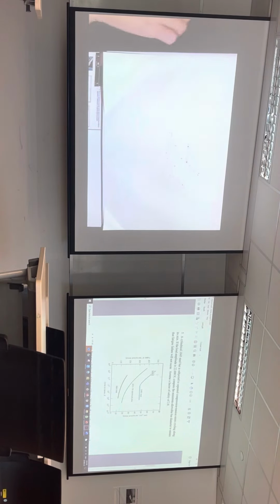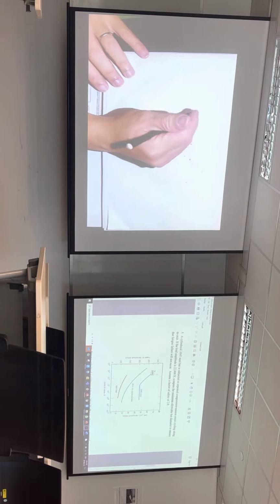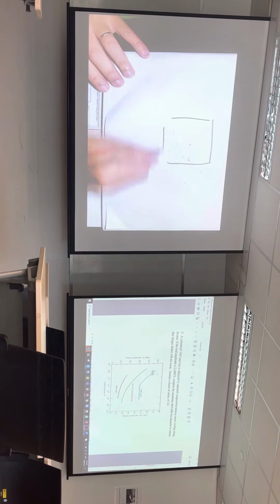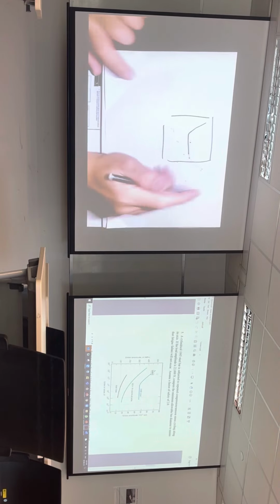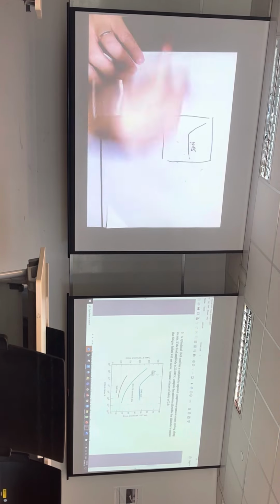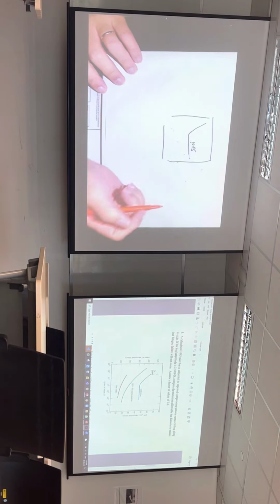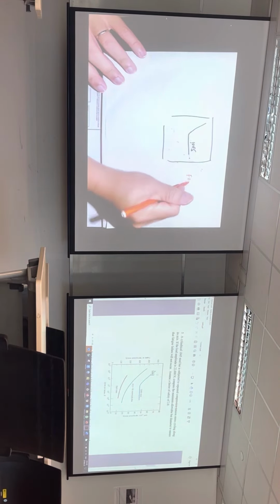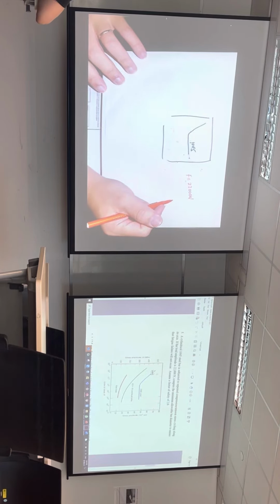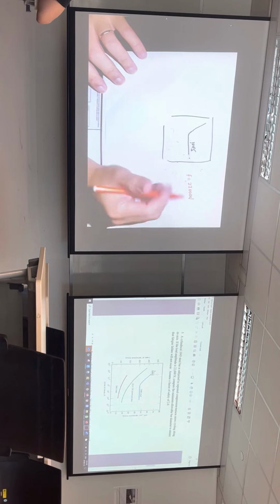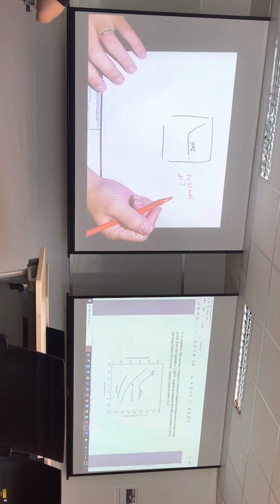Now coming back to this question. So I have 1045. If a load amplitude F applied is 2200 newtons, calculate the minimum bar diameter. So find the diameter allowed to ensure that fatigue failure will not occur.